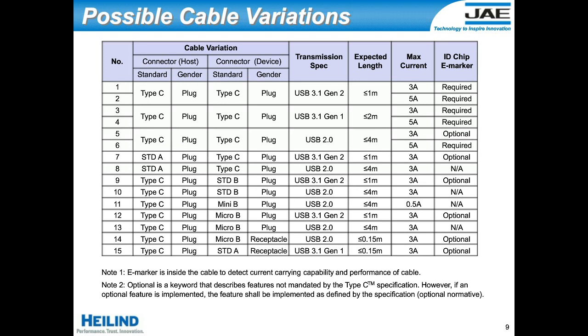The pull-up or pull-down resistors help the devices identify which pins on the Type-C connectors are active, and also how much power is available to be transmitted. Even though most of these legacy cables are capable of 3 amp current, all the devices should be operating at the default USB power levels, which are well below 3